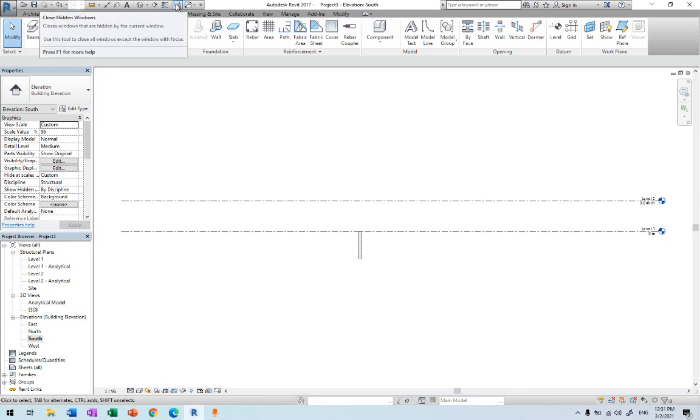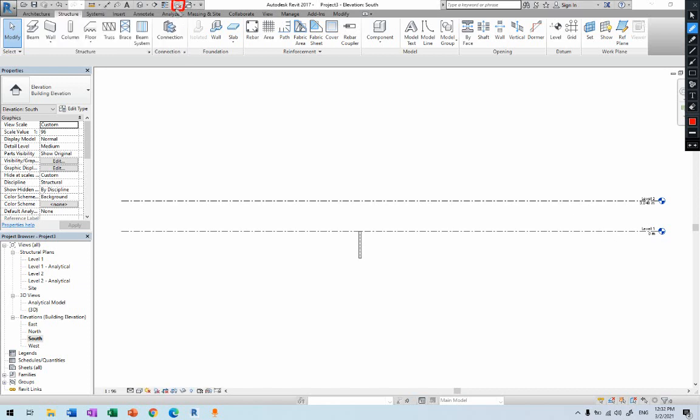At the status bar here, I just simply say close this one here. We prefer to click this one frequently in order to make your Revit faster, because there will be a lot of open windows if you don't close them. In that case, you will struggle with some slow motion in the work.